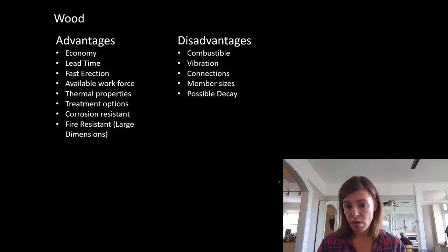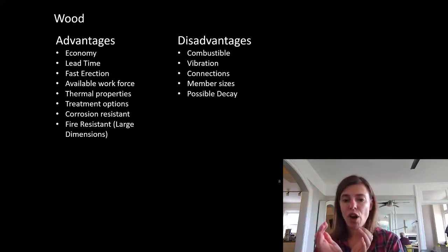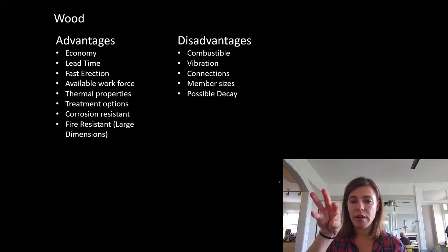It's not as strong as the original amount, definitely not, but in a fire, you're not going to be experiencing your full loads. So we're talking after a prolonged burn. Let's say our building has been burning for an hour and has a layer of char around it, and we've still got good solid wood in the center.